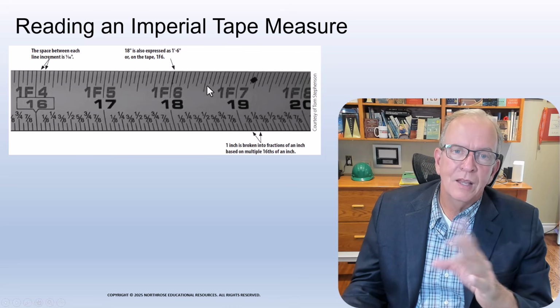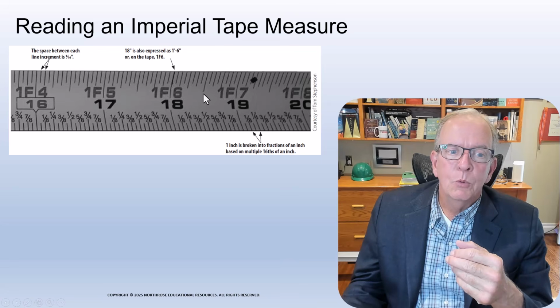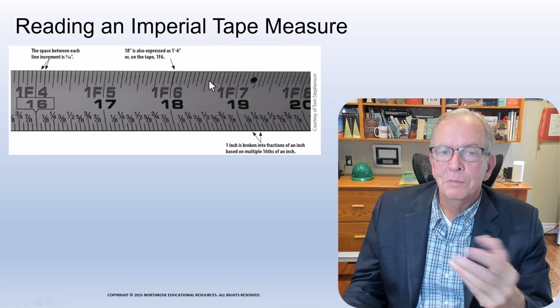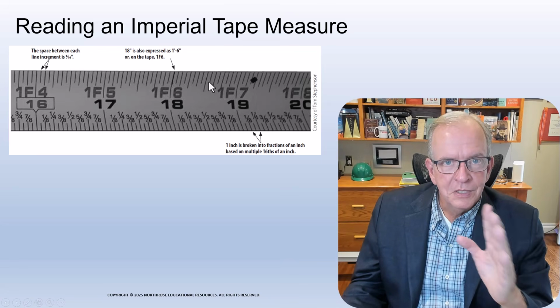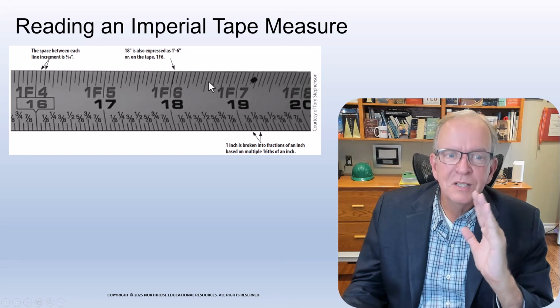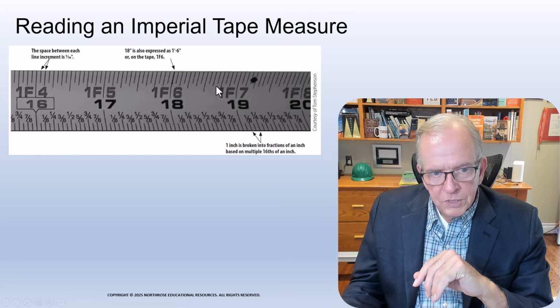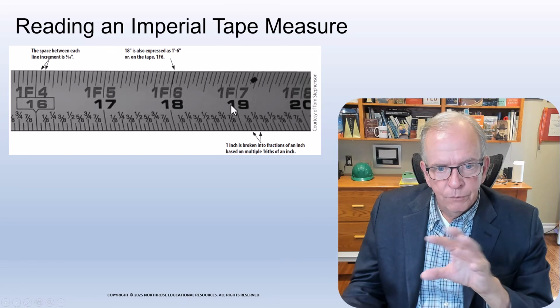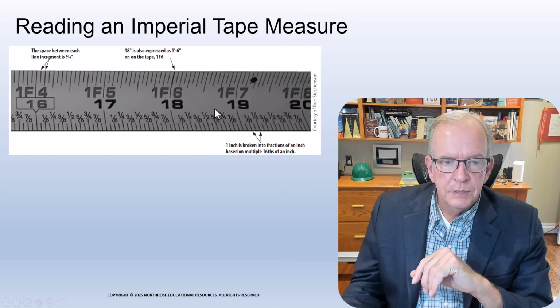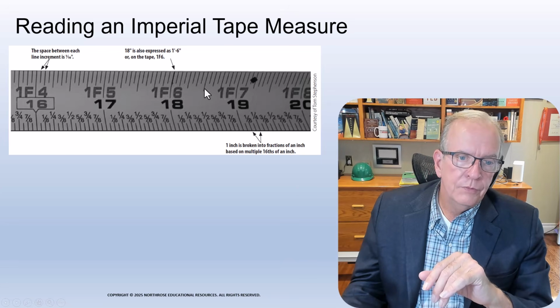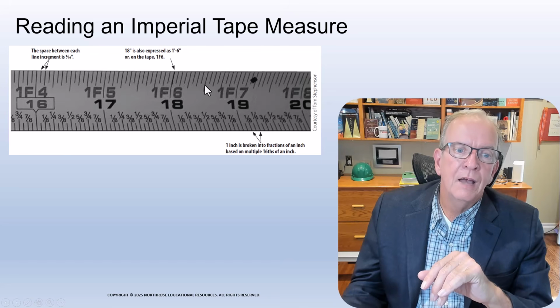A little trick that a lot of times carpenters will say is, I want 18 and a half full. That pretty much is like saying almost 9/16. They're just saying just a little bit more instead of yelling out 16ths. But this is basically your sizing for your pieces, right? And if you wanted something slightly less than a half an inch, they might say 18 and a half light.